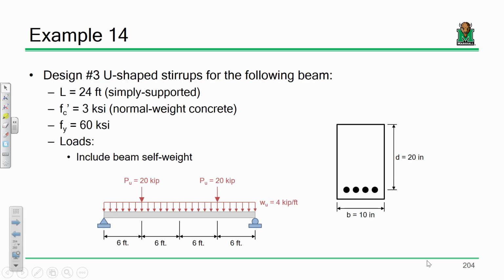Now hold on. What'd you say? Okay, go down to 44. Why are we going down to 44? So this line is going to go down like that to 44 because that's 4 kips per foot over a distance of 6 feet. Is everybody okay with that? Then we're going to drop down 20 to 24. Would you agree with that?